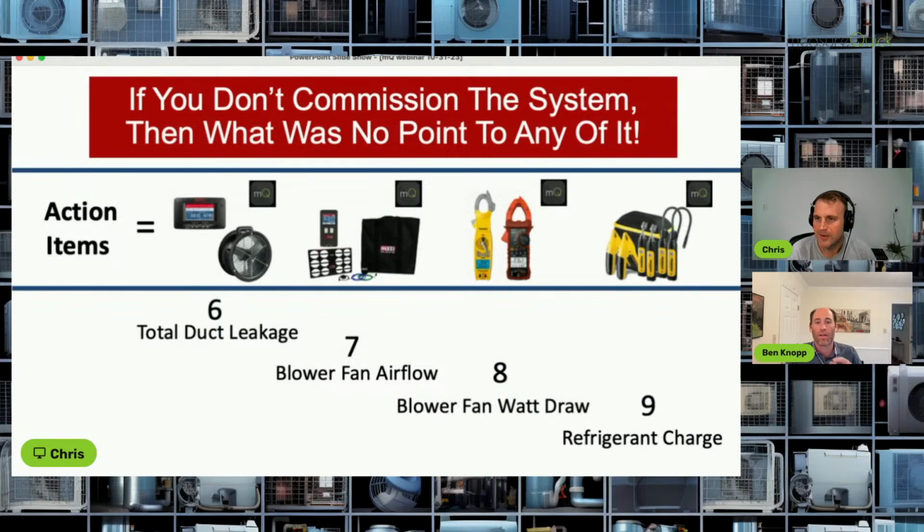And actually, Chris, can I go on a rant about Manual M some more? So when you do a Manual J and you've got your total cooling load in our climate that's humid, you have to design to the cooling load, because if you, like we were tempted to do, try to design to the heating load and try to do it without any electric resistance heat, it hurts you on the cooling load.